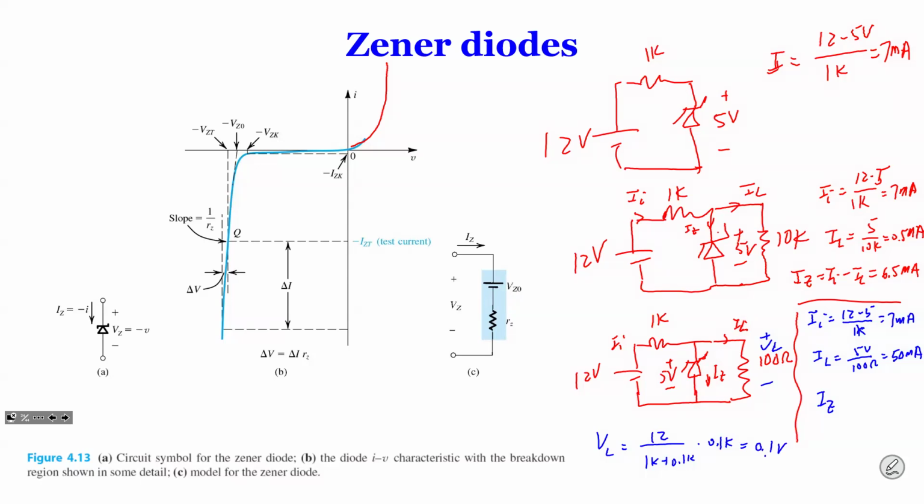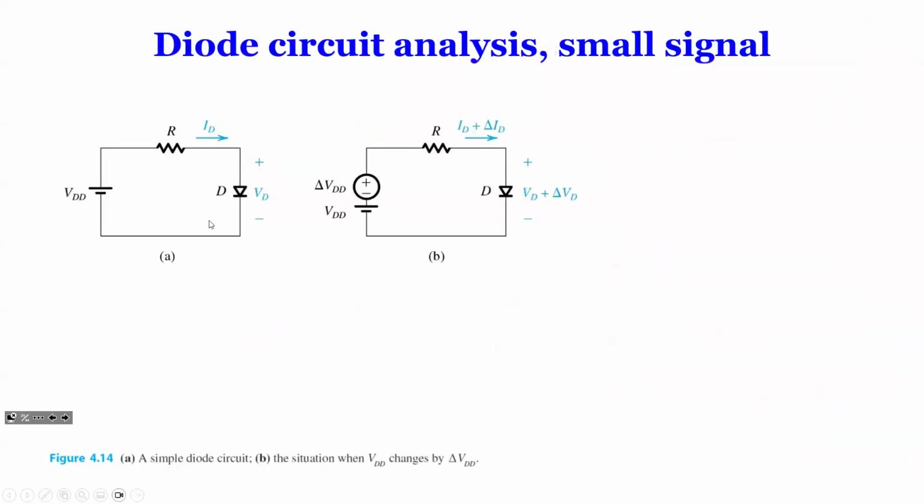So even though you have a Zener diode, most of the voltage dropped on this resistance because the Zener diode didn't get much current. So the little current goes this way, and then there's no current here. So the voltage over here is not 5 at all. It's less than 0.1 volt, because the Zener diode, again, doesn't have current. So now you understand, for the Zener diode to work, you have to flow a certain amount of current in it. If you don't have current flowing in it, it will not stabilize the voltage. So that's the conclusion you can make. The Zener diode is relatively simple, not much to really talk about.